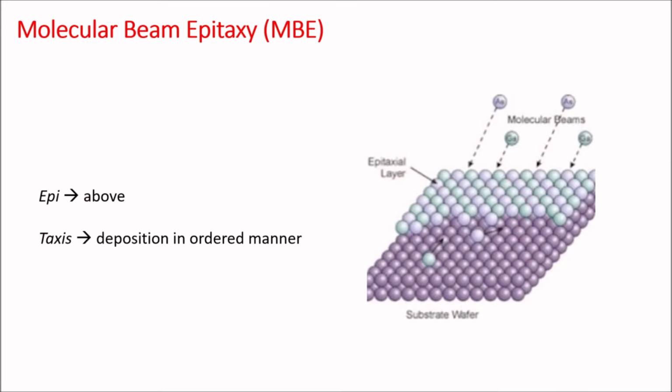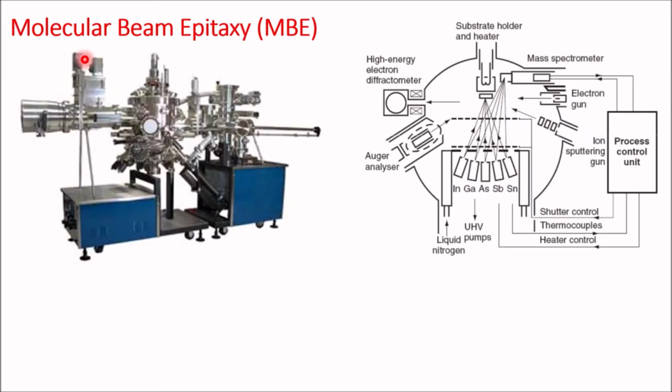Epitaxial films can be grown from gaseous or liquid precursors. The substrate here acts as a seed crystal, where the crystalline lattice of the substrate provides the template for the growing layer to orient itself. Lattice matching between the substrate and the growing nanostructures plays an important role in the fabricated nanostructure. Molecular beam epitaxy is a widely used method for epitaxial growth of quantum confined structures.